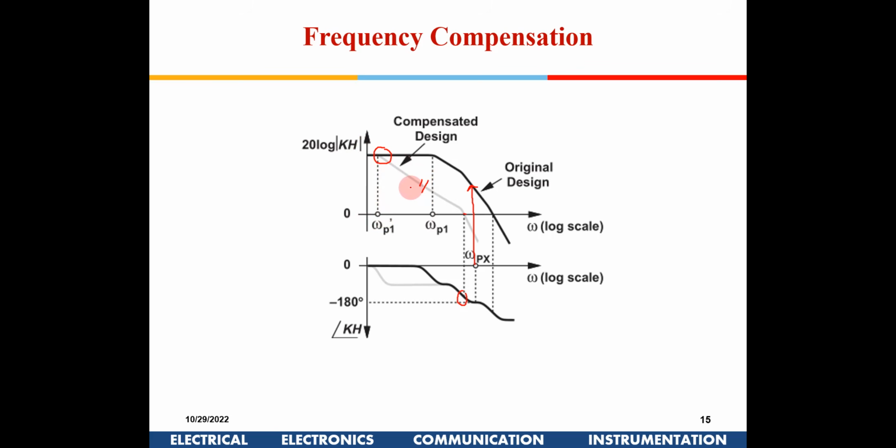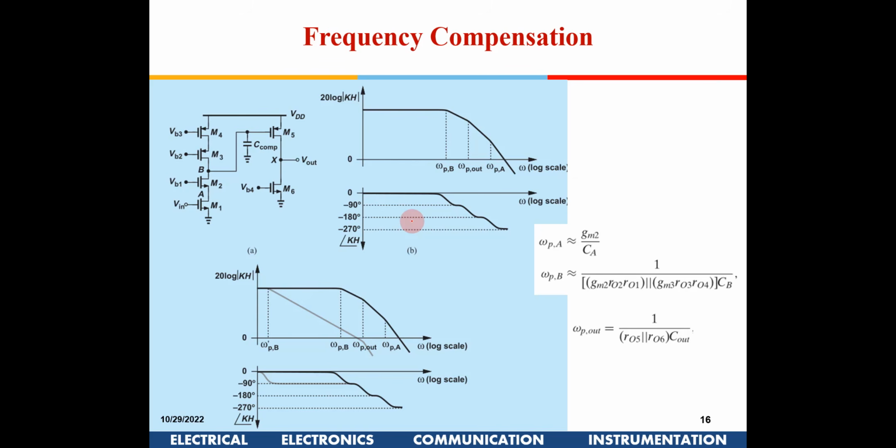So from the original design, we have removed the previous RC components, and we are replacing them with only one. I have added one more capacitance. I'll show you the circuit diagram. Now this is one amplifier. This is the second amplifier out here, right? So this was the original. There were 3 poles out here. Suppose there is one node here, one node here. Now what I am doing is putting one more capacitance out here, an additional capacitance, which is a dominant capacitance.